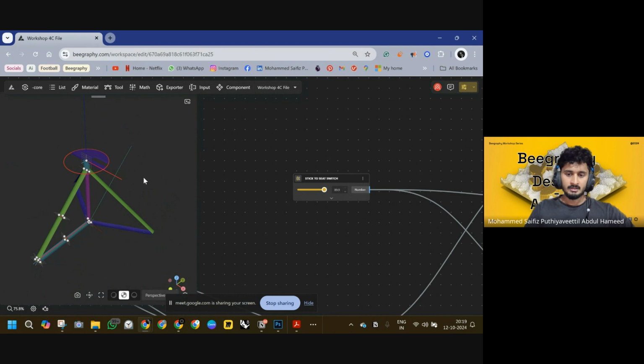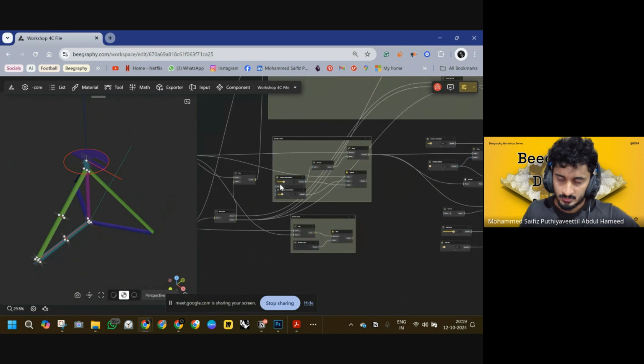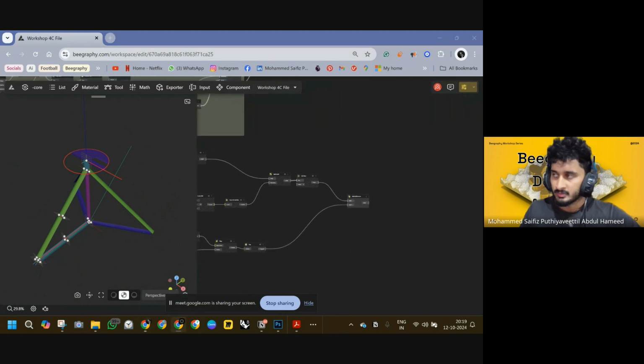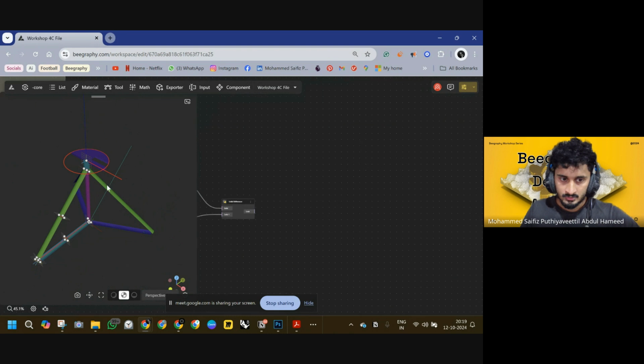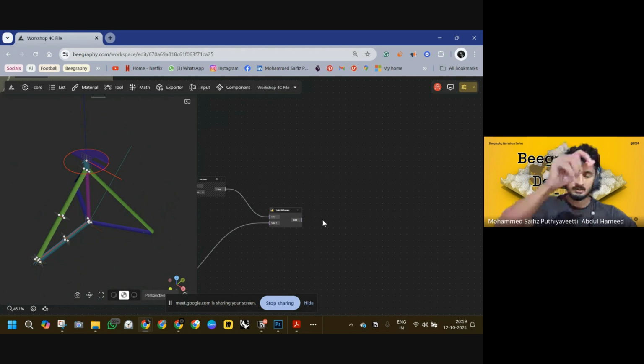And when it's above, it needs to be vertical, so that it becomes a handle. Now, the way to do it is the same. We need to rotate the solid along this axis from 0 to 90, and that angle will connect it to our initial slider.